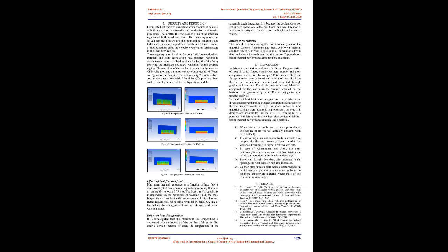The heat transfer by radiation is minimal and negligible, and hence in this numerical study radiation effects are not considered. The governing equations are the standard continuity equation for conservation of mass, the Navier-Stokes equation for conservation of momentum, and energy equations for predicting the conjugate heat transfer. The following conditions are assumed in this numerical analysis. The mass of a fluid is conserved. The rate of change of momentum equals the sum of the forces on a fluid particle, Newton's second law. The rate of change of energy is equal to the sum of the rate of heat addition to and the rate of work done on a fluid particle, first law of thermodynamics. Flow is assumed to be laminar and incompressible.